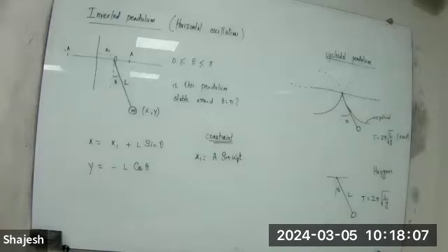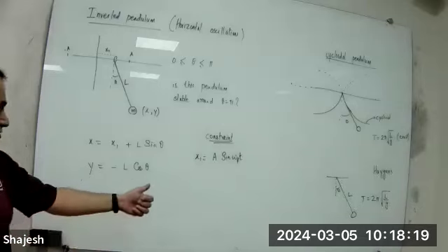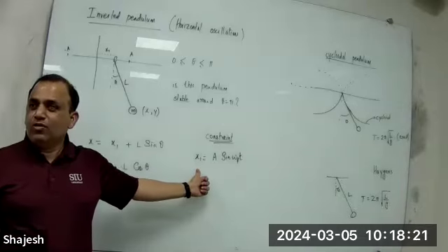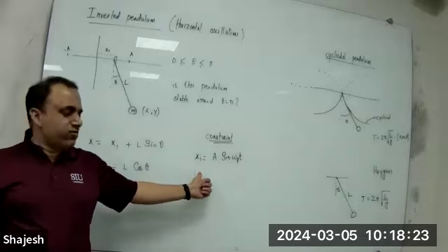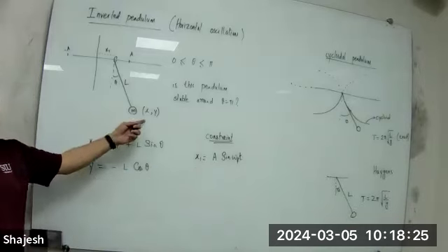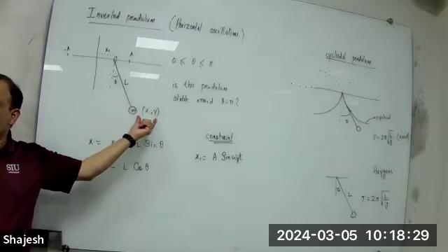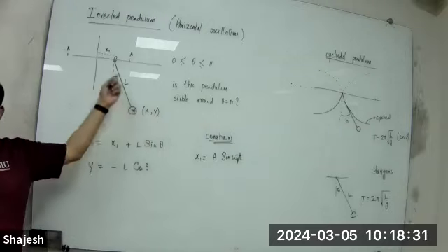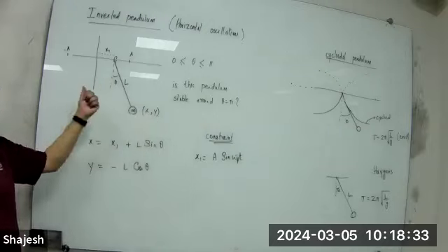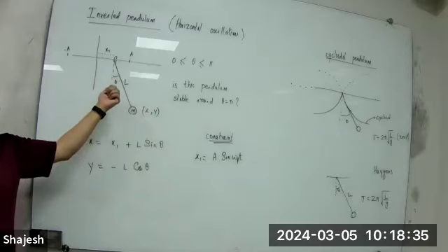Which coordinate among all this, x, y, theta, x1 and so on, is there a choice for the system? Angle theta, correct? x1 I have decided now because I don't have a choice. For X and Y, there is a freedom there, but there is a constraint of L. So a suitable coordinate is angle theta.